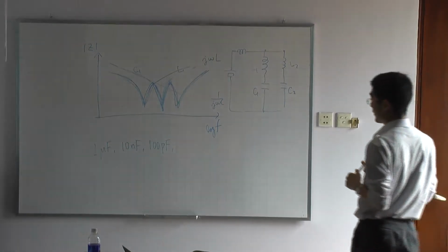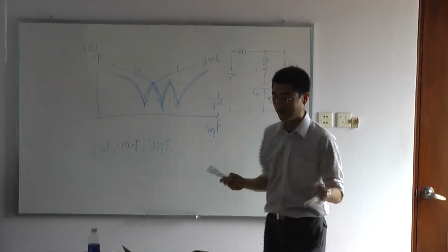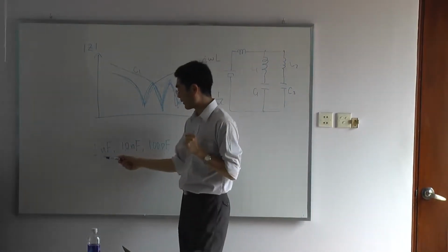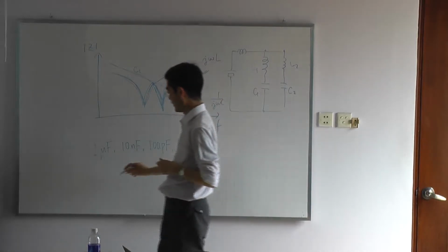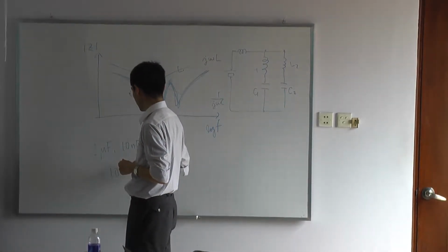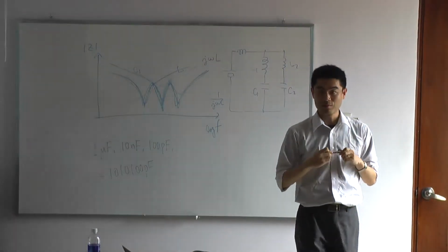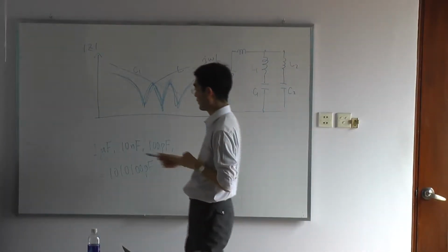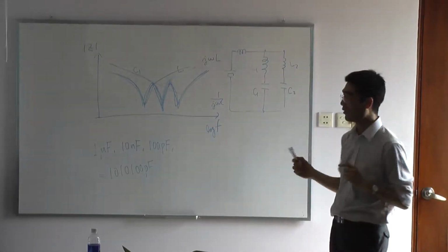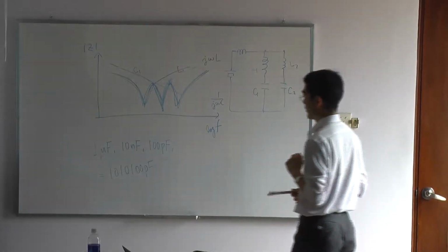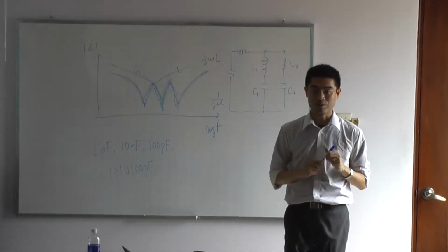So the first time, if you see that, I put 1 microfarad, 10 nanofarad, 100 picofarad in parallel. That is equivalent to putting this amount of capacitance. It doesn't matter if you have 2 microfarad, it's okay. Putting one large capacitance is okay if there is no inductance.